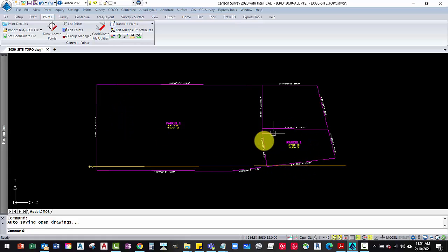Down here in parcel 3, there are all kinds of points in this area. One of the methods of doing that, and probably the most common one, is to bring in all the points, sort those points into point groups, and then plot those point groups. Then you'll see what I'm talking about. You're looking at a lot fewer points to work with. So we'll pull the building points in, and then we can actually draw the buildings.